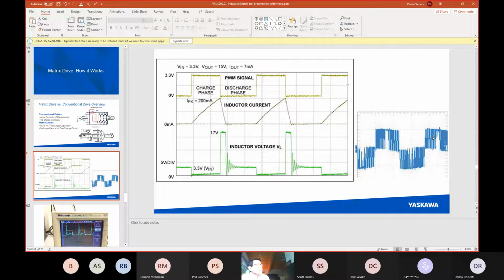Over here, this is a full phase of pulse width modulation. These are the individual pulses. But here, the current would climb, peak, and then start to descend. And that's the sine wave that we're talking about for the current in the induction motor.